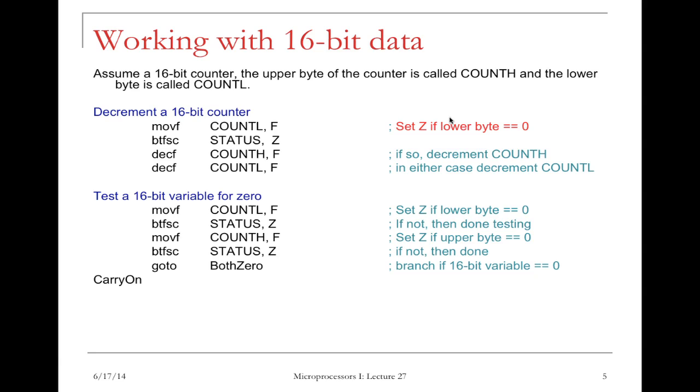Let's say this case is not a 0. Okay? It's not a 0, then this 0 flag will be a 0 to indicate it's not a 0. The second instruction, BTFSC. Bit test a register, skip if that bit is clear. So in this case, the 0 flag is a 0. Indicate this 5 is not a 0, right?